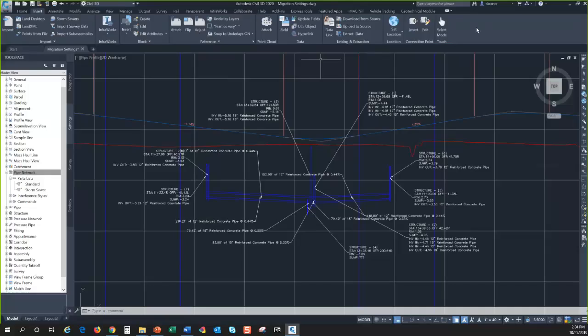Did you export the drainage areas from CAD using the watershed tools? No, I didn't. What I did is I developed those drainage areas. My surface was very, very flat, and the tool for catchments in Civil 3D doesn't do flat real well. So what I did do is I used the water drop command to develop those and use polylines.